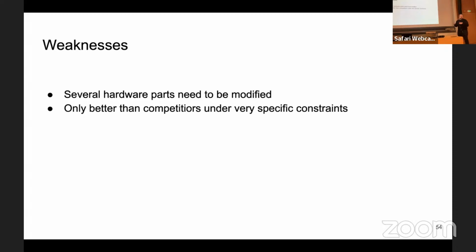We would activate the row once with sectors 1, 2, 3, and 4, and then issue read commands that read a cache block and access the data stored in sectors 1 and 2, and then a different cache block in the same row and access the information stored in sectors 3 and 4. But if, in both cache blocks, we store that relevant data in sectors 1 and 2, then when we initially activate the row, we only have to activate sectors 1 and 2, and that makes things more efficient. Does that explain it? Yes. Thank you.